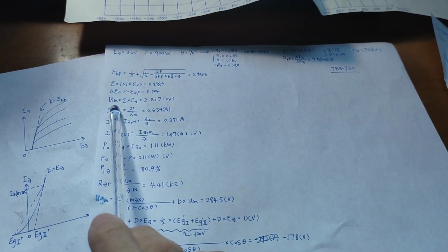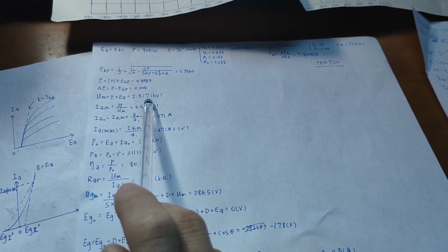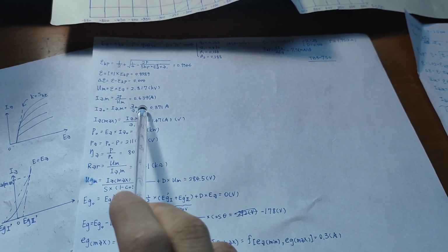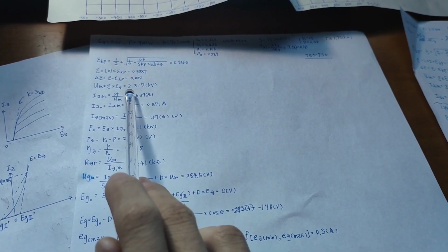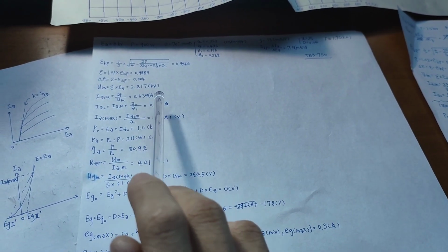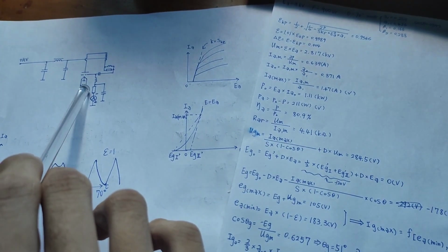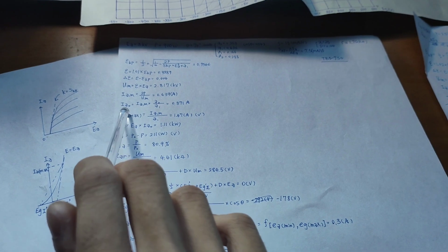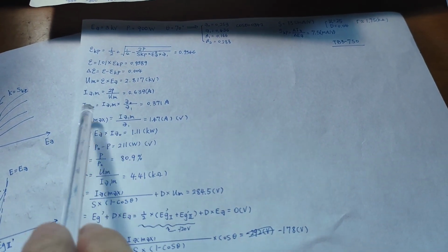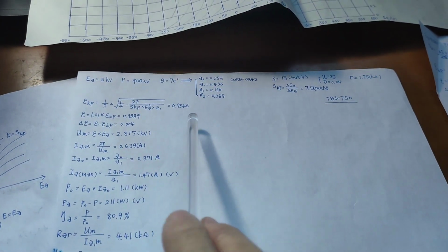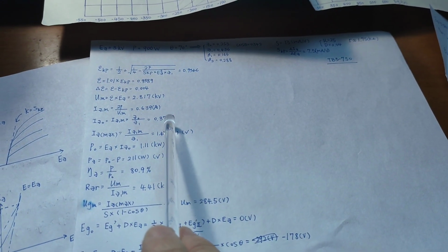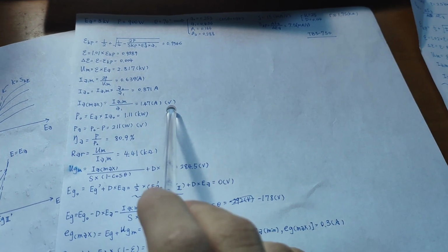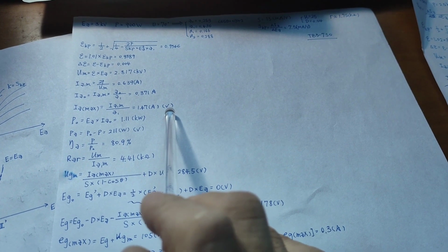And the maximum voltage appearing on the anode will be this. You can calculate it by using this and the anode voltage, and the maximum anode current is this, the peak current. You need to make sure that this current is less than what your tube is capable of. Your cathode emission needs to be larger than this number. And this, I do not know how to say it in English, sorry, but you can simply see that we can get this number from this one, and a ratio between these two values, right? Get this one. Oh, sorry, that is not the maximum current. The maximum anode current is here. You can see I just checked it because it's under the capability of my tube.